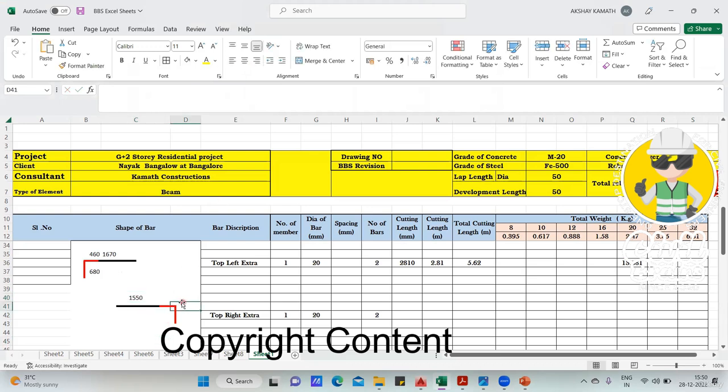How much is this portion? This portion, 500 is a column distance minus 40 mm cover I do. So it will be 460. Select on that and bring it to this portion. Okay, if it is not coming exactly, just drag it. Okay, done. Now what about this portion? It is 57 into diameter of the bar, 20, minus this 460. Enter. So it will come here.